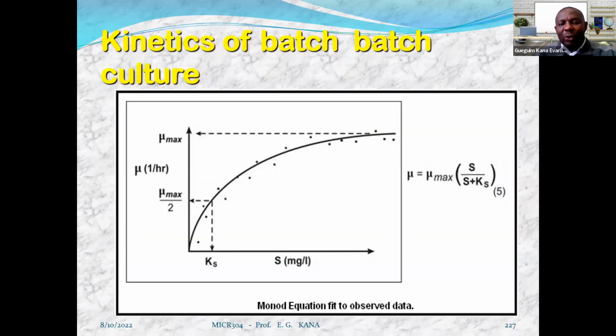All right, great. We're back with our Monod equation here. There are a number of pieces of information that we can derive from it. The first very visible information is what? Mu max. If you project where there's a plateau of your graph back to the y-axis, the mu axis, we're going to have what is referred to as your mu max. Mu max here is in actual fact the maximum rate of growth of the cell, or it's called the maximum specific growth rate. Take it as the maximum rate of growth of the cell. They can't go above that. We already obtained one very important parameter, mu max.